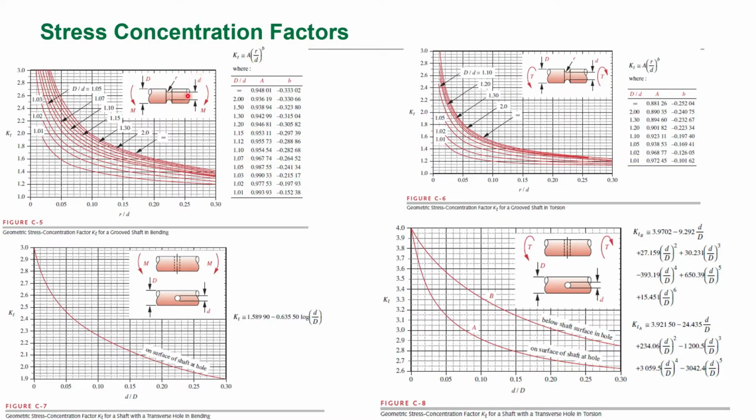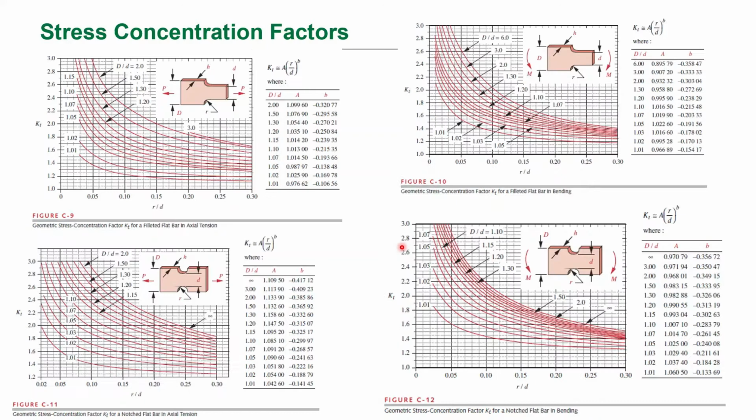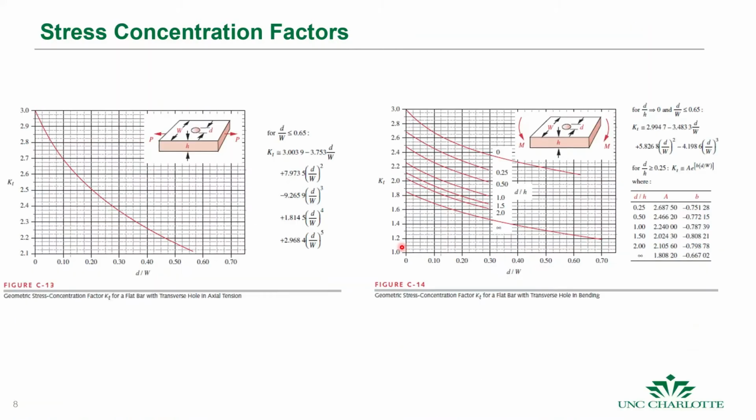In this case here, again, this is a shaft with a groove, applied moment, stresses go up to 3, and then we have this applied torque, the same thing, okay? And these are just different geometries. This is a shaft with a hole, all right? And you see that we can calculate these stress concentrations for those. These are plates with different features, step change in height, groove.